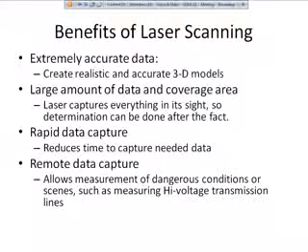It allows us to measure such dangerous conditions, for example, high voltage lines. In looking at it from more of a civil standpoint, when we're putting together, say, a bridge and we need to bring in fairly large components, we can use Navisworks to map out not only the direction these components would be brought, but we can use laser scan data that would show us the route, so we can determine if there's going to be clearance between maybe some high voltage lines in the area, rather than trying to rely on maybe outdated maps or pictures, or even try to bring someone out there to accurately measure that. We can bring out a laser scan, take a very accurate snapshot, incorporate that into our Navisworks model, and then we can utilize that with some of the planning process.